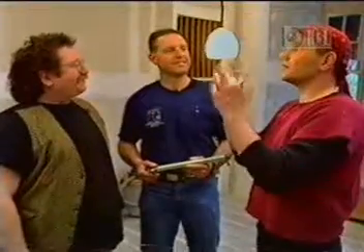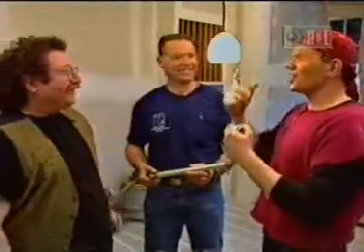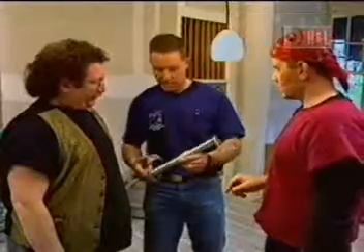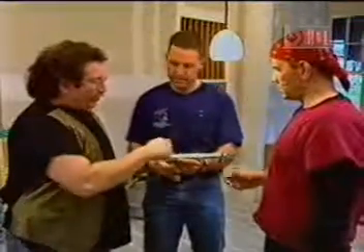This is a light pendant, though. What if it was a ceiling fan or a heavy chandelier? What would you do then? Well, then in your existing ceiling, you'd cut a 4-inch diameter hole. Insert the crossbar up through it. Oh, a support bar like this.